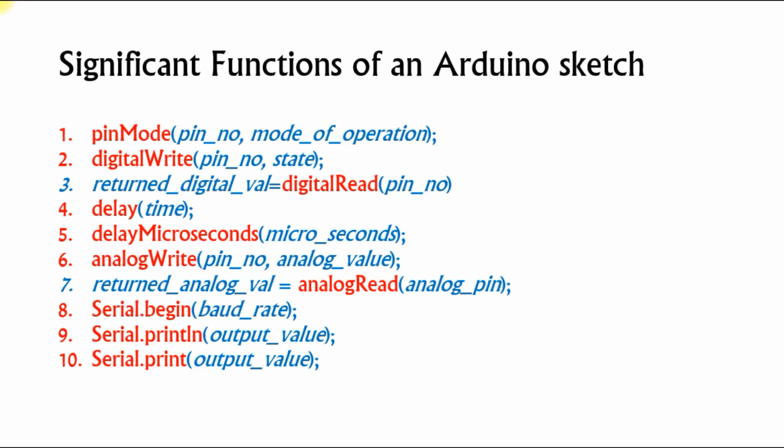And the 8th, 9th, 10th lines are all serial commands: Serial.begin baud rate, Serial.println, Serial.print. Serial is actually a class in Arduino. If you are writing the code and sending the code to the Arduino, this is serial communication from computer to Arduino, right?